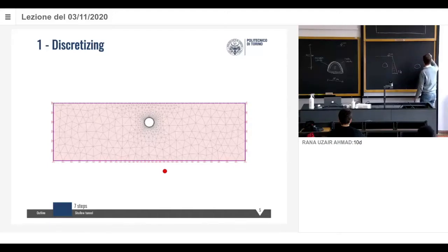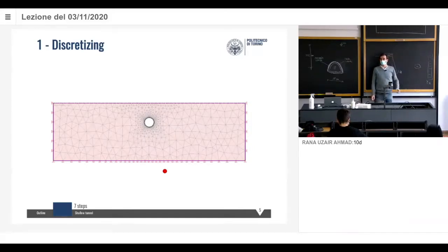And then we will apply something like this. Constant with depth. We usually say, okay, gamma times z, but z is the z at this point, and we keep it constant all over. In fact, when we use the Kirsch solution or the Carranza-Torres and Ribacchi solutions, this is what we're doing. We are considering that the state of stress is constant all over. Okay, so that's the difference between shallow and deep tunnel. Now let's go back here.